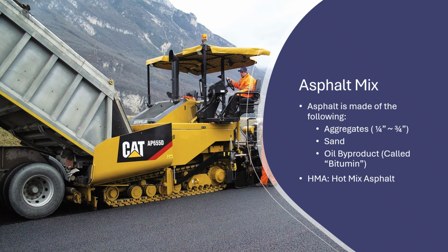And then the last thing you'll see is an oil byproduct, which is called bitumen. In mix designs, it's called a binder. There's different types, there's different specifications, but all it really does is hold everything together. And so to use another food reference, if I'm baking a cake, I'm going to mix flour and water and milk and maybe a few other things. But really, it's the egg that holds everything together. And so we can look at oil in that sense.